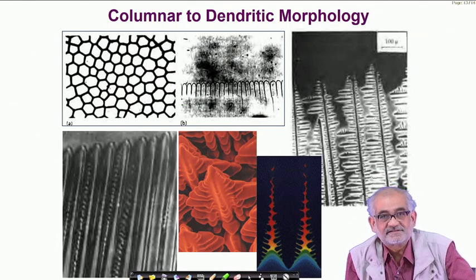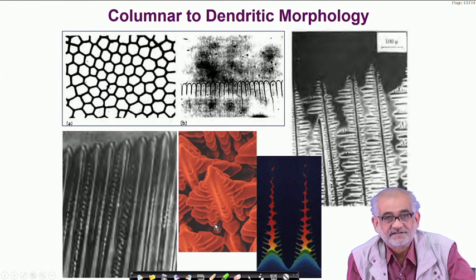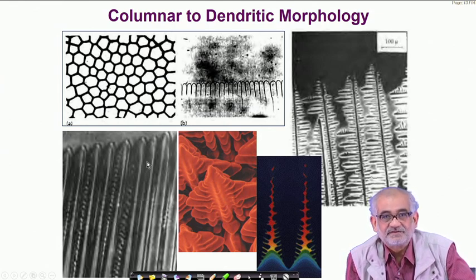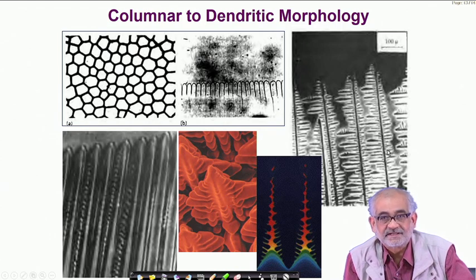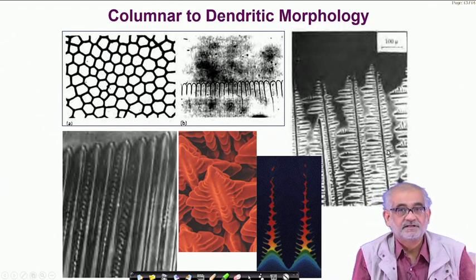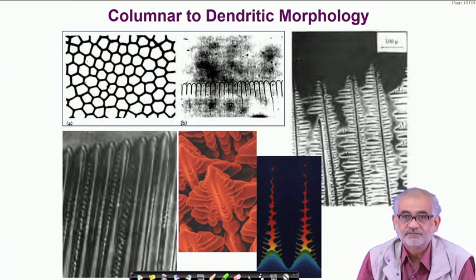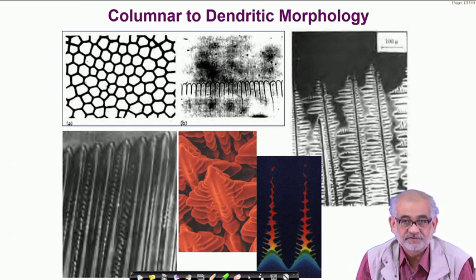So when we cast, these are the kind of fancy structures we see, not always, but we may end up seeing such growth of columns, and at times those columns, which are unidirectional in growth, can also manifest a similar tendency of growth in the lateral directions, leading to what are known as dendrites, a term borrowed from the Greek word meaning fir tree-like structure.